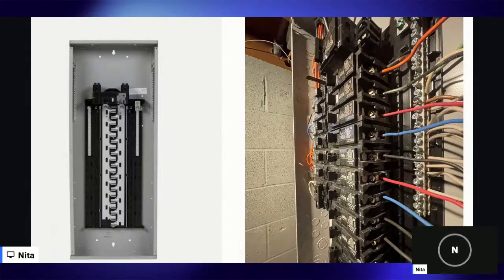The grounding bus bar is where all of our grounding wires, which are either bare copper or green, connect. So in this example, this is our neutral. We would have white wires here. This is before any breakers, right? So this is just showing you the bus, and then this is showing you the bus with the breakers and the wires. So main bus, main highway, where our breakers are attached, neutral bus bar, grounding bus bar.